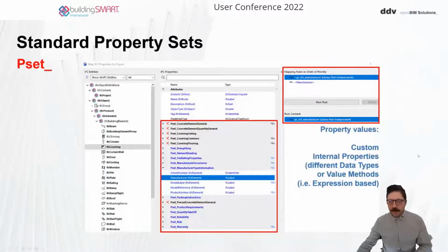And also let's talk about the standard property sets. The IFC schema is a standardized data model, right? And there's a bunch of standard property sets that most of the time are underused. So in ArchiCAD, you can preview most of those standardized property sets, and you can predefine the values of each of the properties stored within each of those property sets.